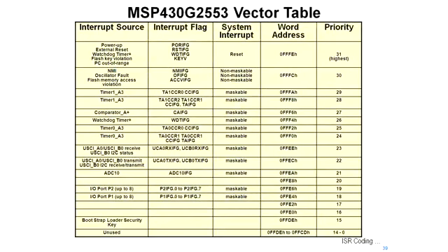The G2553 vector table looks like this. Starting up at the top at FFFE, in order to program that in. That's FFFE and FFFF. You'll see that the reset interrupt is there.